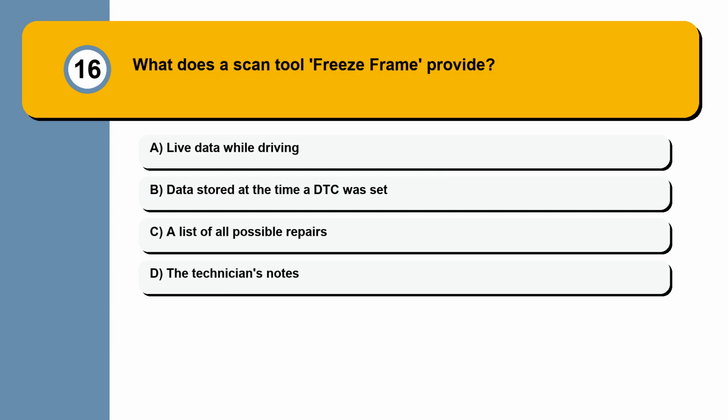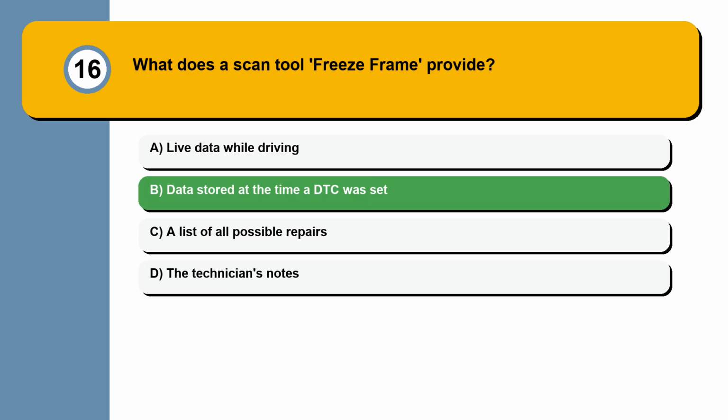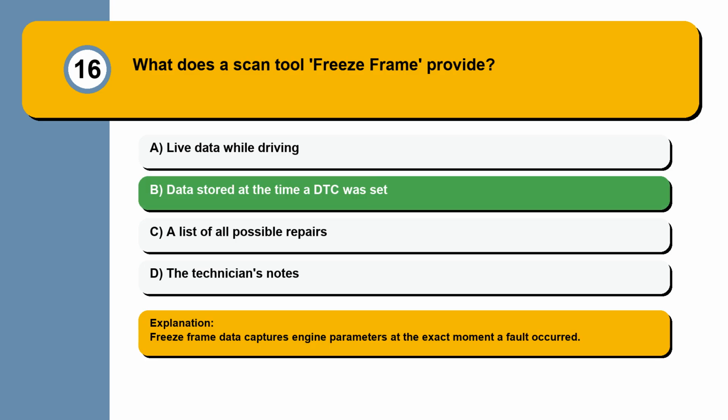Question 16. What does a scan tool freeze frame provide? Live data while driving, data stored at the time a DTC was set, a list of all possible repairs, the technician's notes. Freeze frame data captures engine parameters at the exact moment a fault occurred.